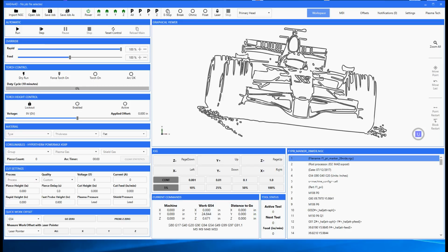Now, if e-stop is triggered just like version 2, it'll be solid red. Now, we've done all this. We could park the machine back to the lower left or whatever action, just like version 2. Breakaway, this is dual action now. If you're running the machine and the torch breaks away, this will go solid red just like version 2. However, if you want to override, let's say the machine cruises along and something happens, a tip up or whatever, and the torch gets knocked loose, the machine's going to stop. This is going to go bright red. The torch override now is no longer a separate button.